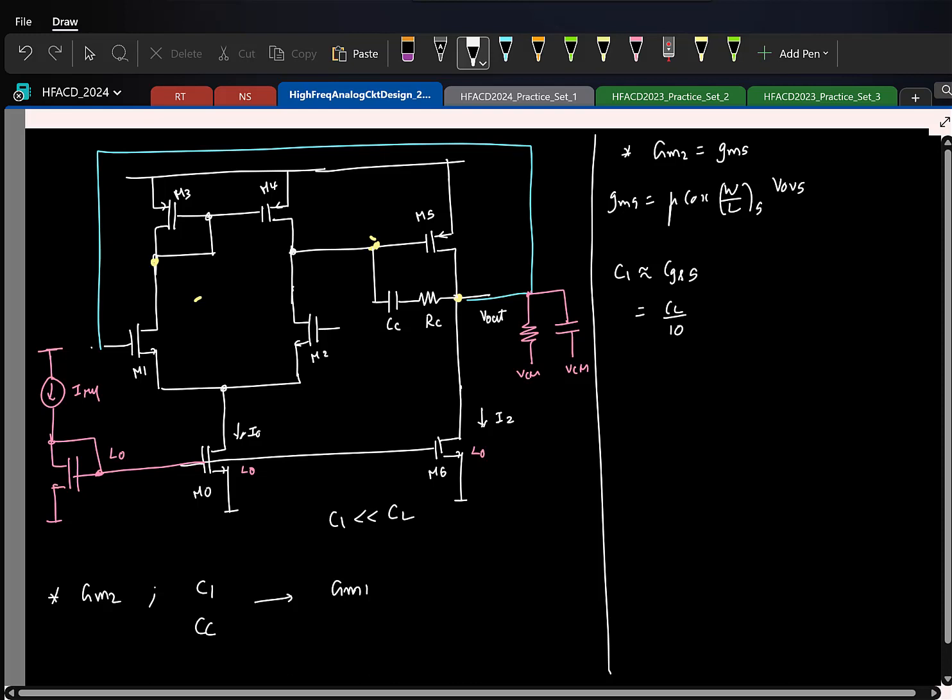And what is CGS in terms of the transistor properties? Do you remember? It's proportional to area, so again you can do it. It's basically W L COX. COX is a process constant. So from this you can typically find my area, W times L. Now once again, I need to separately find the width and length. I know only their product. What can I do? You have to assume, and typically you can assume the length.